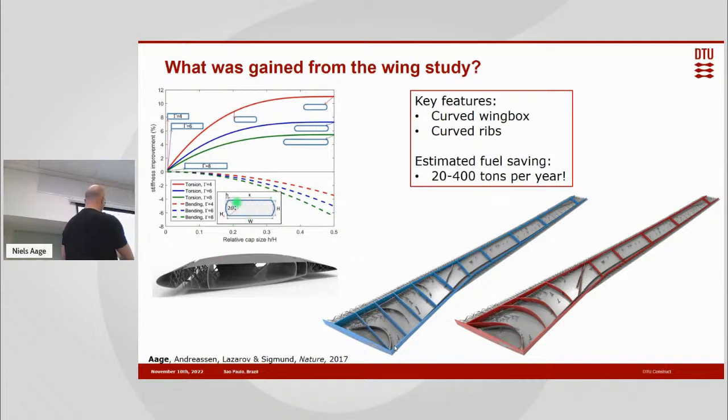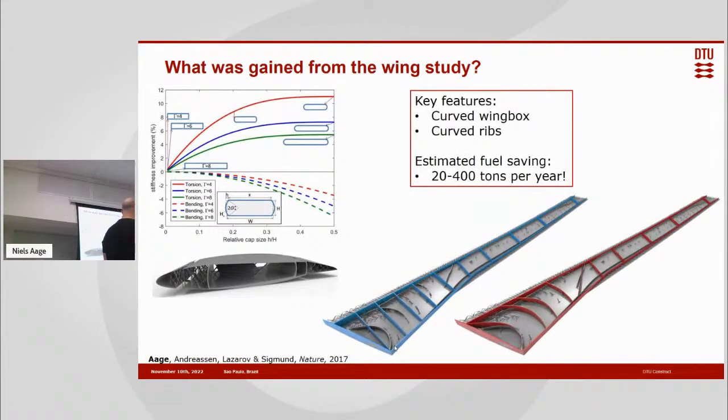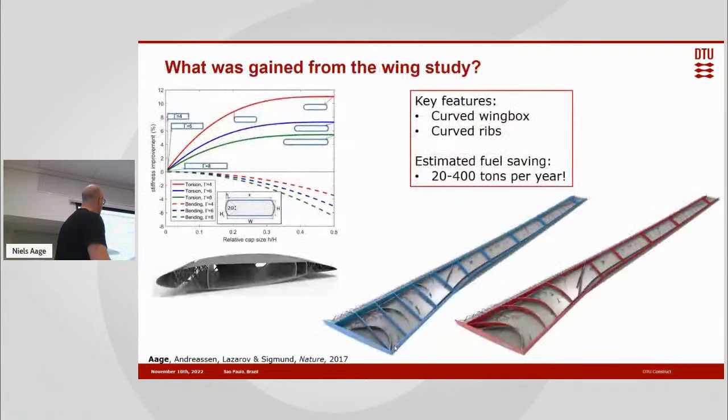So we did a small study on that, pure analytics, and then we also took a regular layout of a divider of the wing, so you can have the fuel, so it's not going to fly around with two big bathtubs. We just divided that in a slightly different way. And what was changed? Just by these two features, not all the other fine stuff, we see that you get a 2 to 5% weight reduction for the wings,